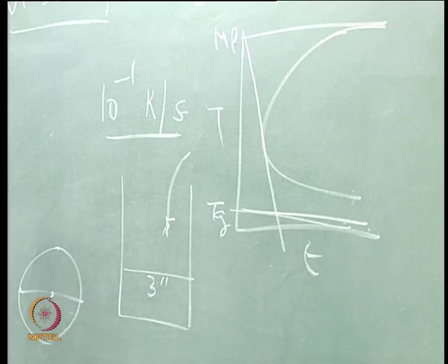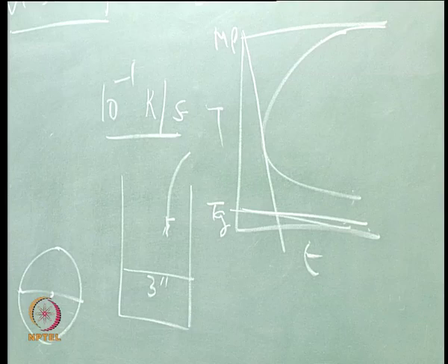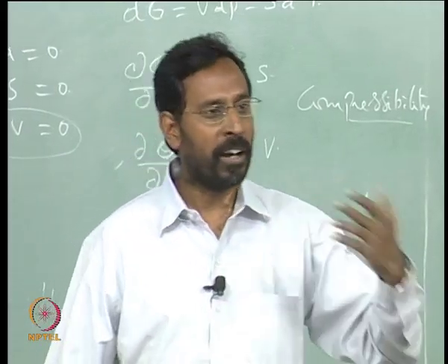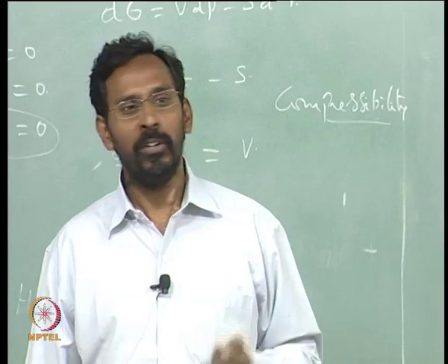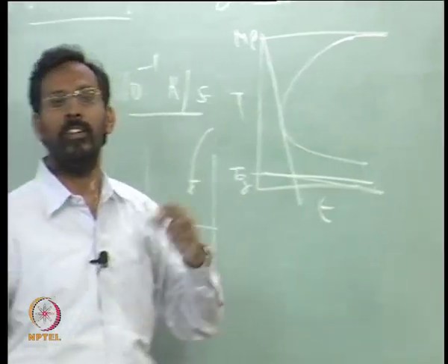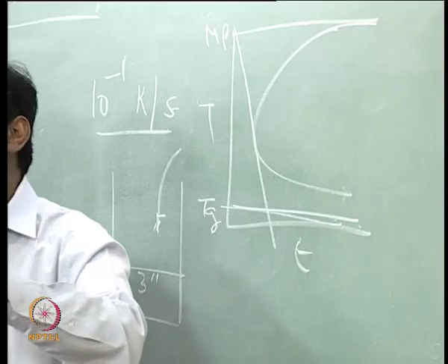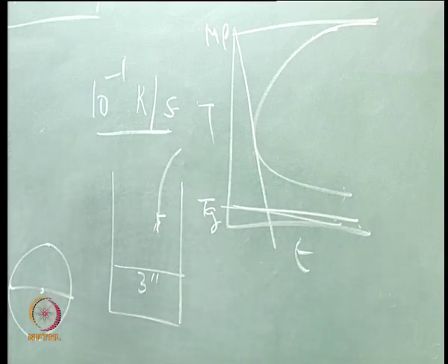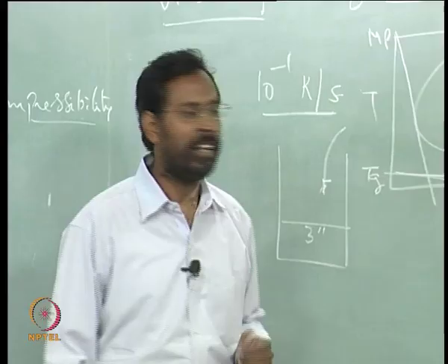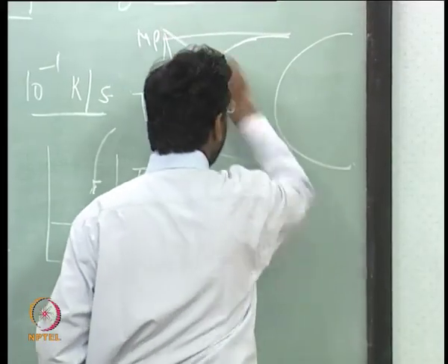Similarly, you see even in martensite, when you add an alloying element, the curve shifts. Why does it shift? Because diffusion is made more difficult and the pearlite formation is made more difficult. Whenever you add chromium or any alloying elements, you see that the TTT diagram shifts, because the diffusion is more difficult. That means the time required for the pearlite to nucleate is longer. Similarly, if I add more and more alloying elements into the liquid, this curve shifts like that to an extent that